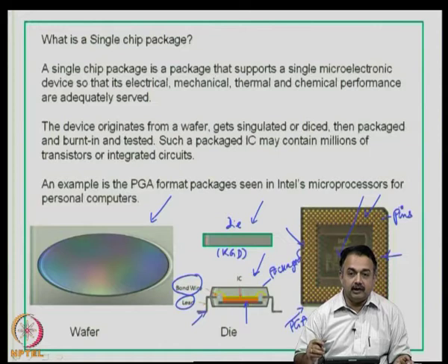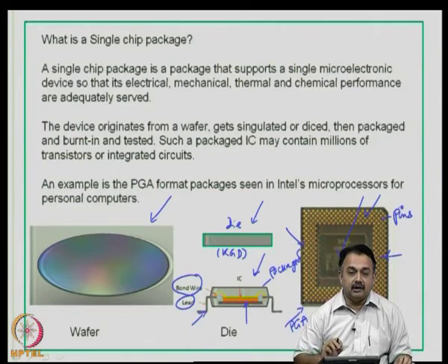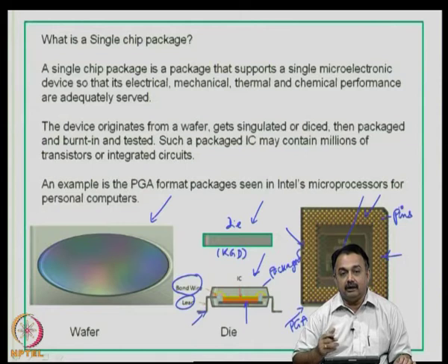Some of them will bring in a ball grid array format, and some others in a QFP format. That depends on the number of IOs and also the pitch. I hope you remember what a pitch is, and pitch is going to be a very crucial decisive factor in determining and custom building your format for the IC packages, because the industries are going to make it in millions.